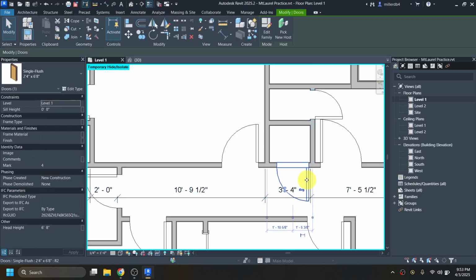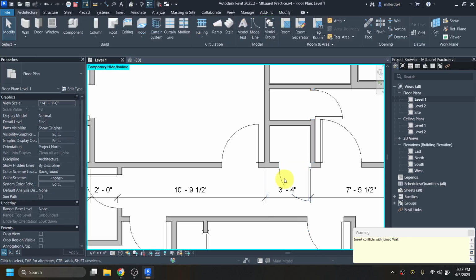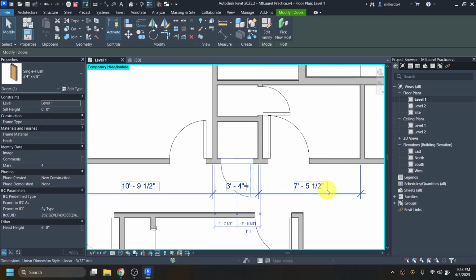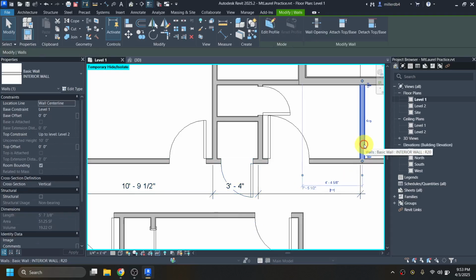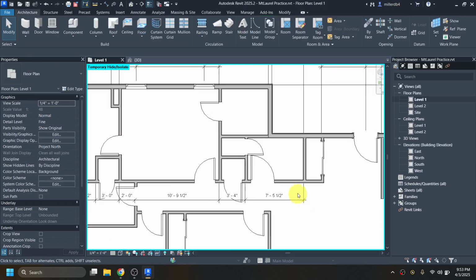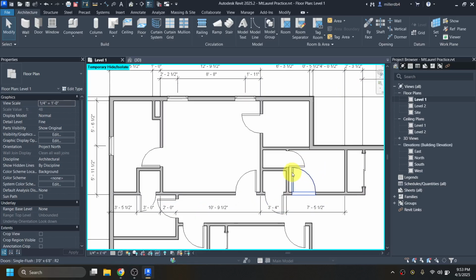Sometimes you may get like an error code, like I'll try to this. Maybe you move the wall and your door's in the way. You can just click on that door and use your arrow keys to kind of shuffle that door over. We'll go to this wall to adjust this number, but that number happened to already be correct. That was just a little bit of happenstance. I guess not too much though, because it was dimensioned here to where to get to it. Okay, and then I'll do another big interior chain.